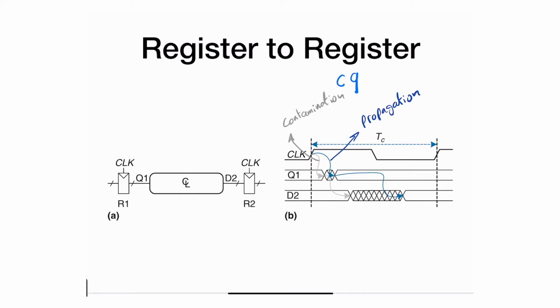any analysis I'm doing right now doesn't worry about the logic or the functionality of the circuit. In this circuit, we don't know what the combinational logic is, and we don't care about it. Technically I don't know what this circuit is doing. All I care about is that it might be a part of a larger circuit, and that it starts with a flip-flop and ends with a flip-flop. I just want to make sure that the timing constraints for this particular flip-flop are not violated.